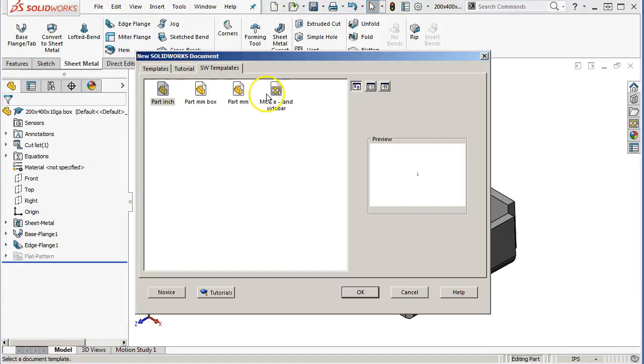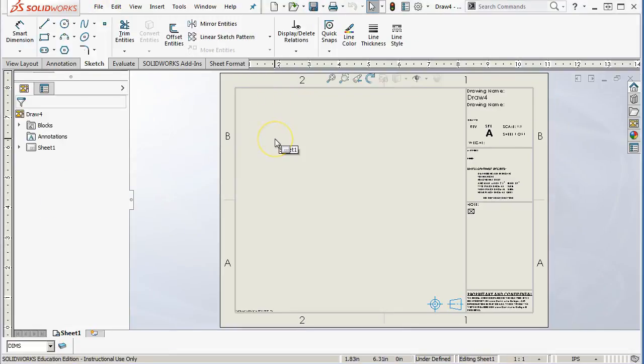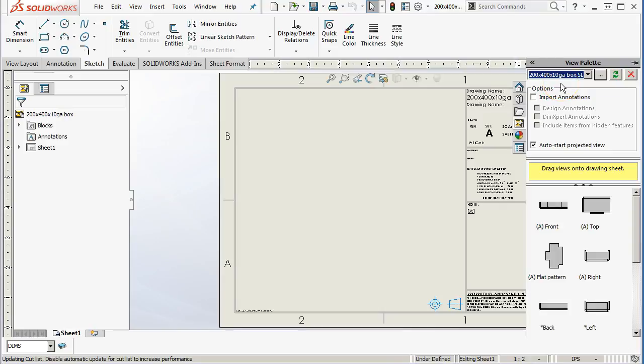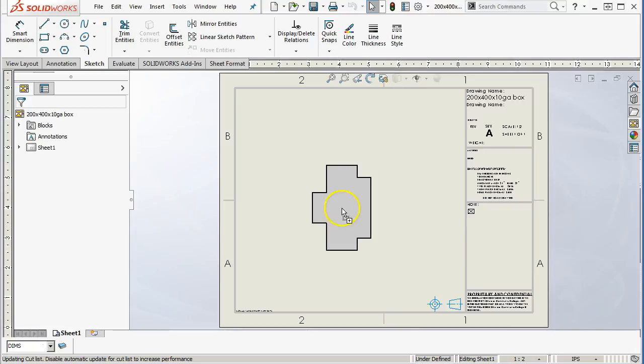All right, so I want our new drawing, and this is where, oh geez, when did they upgrade that? Probably somewhere between 2010 and 2012, sheet metal got a facelift, and one of the things was how they managed the suppression of that flat pattern. I put this in, and I'm not even worried about telling it to go to the flat pattern inside of the part. It's the drawing that's going to create a derived configuration and will ultimately, in my opinion, manage my sheet metal part. So we go in, grab the flat pattern, and place it.